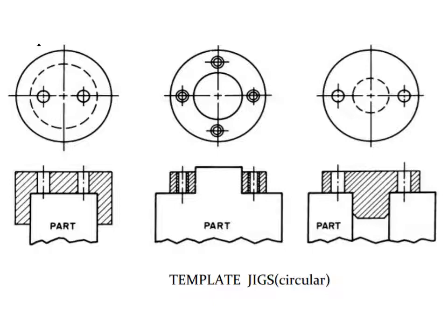Take the first figure where the disc is marked as the part, and the jig is located on the outer diameter of the part, and it is clamped firmly by some screws or by some attaching mechanism, and the part outer diameter is taken as the locating diameter for the jig.